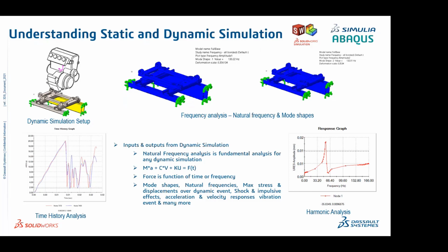So natural frequency analysis is the fundamental for any dynamic simulation. And here, in the governing equation, we are not neglecting anything. So we are going to consider the inertia, the energy absorption, which is basically the damping effect, and k into u or x, which is my stiffness into displacement, and f of t. And the main input with respect to the dynamic simulation is the force, whatever the applied force, right?